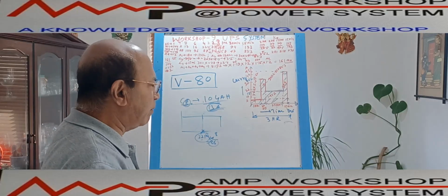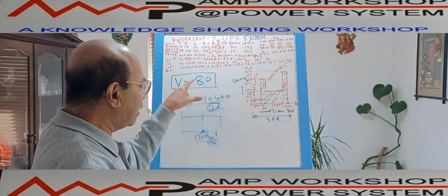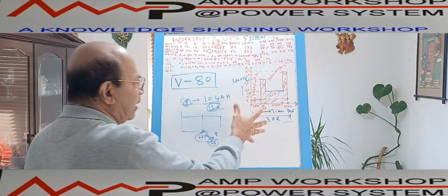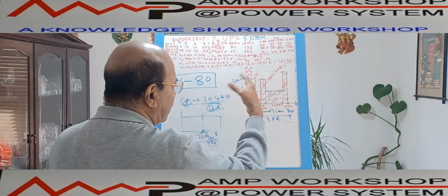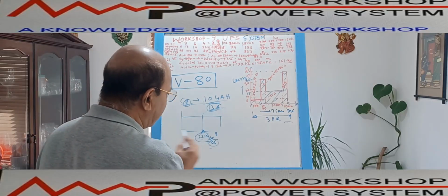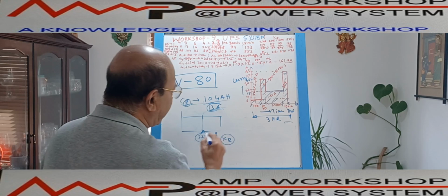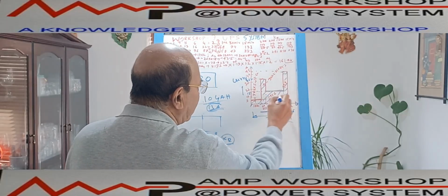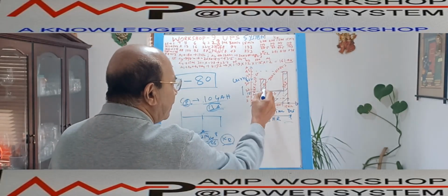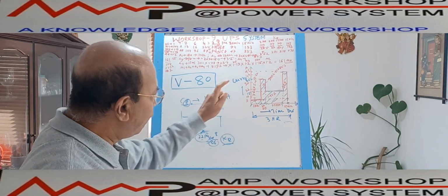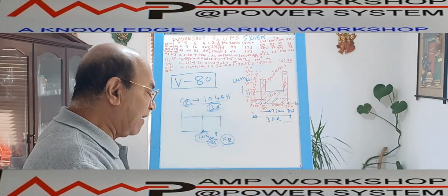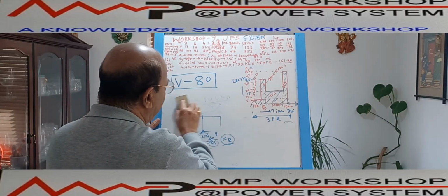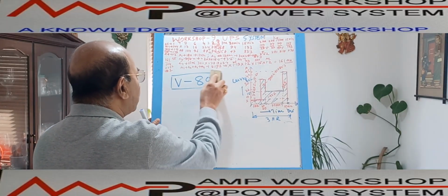This factor we calculated for the constant current, in terms of ampere hour. But as this is a variable current, IEEE has recommended to calculate in terms of current. This rate of discharge factor Kr is to be calculated. For the constant current it is only one time. But here, as the current for each instant is different, for each area the K factor will be different. So for each area we have to calculate the K factor. That is the first job to calculate the ampere hour of the battery when the current is not constant.